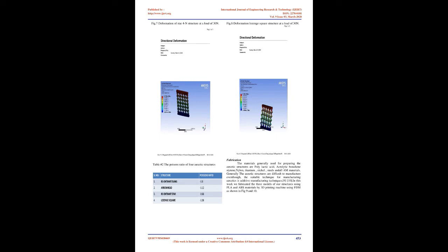Finite element analysis with tensile loading conditions was performed on all these geometric structures using the ANSYS package version 19.2. For each design, the bottom surface was fixed to a rigid structure and the top surface was pulled with various input forces to calculate elongation in the axial direction and transverse deformation. The characteristic strut ratio H/L and reentrant angle have significant effects on the properties of auxetic structures. All the geometries are modeled using NX 11.0.